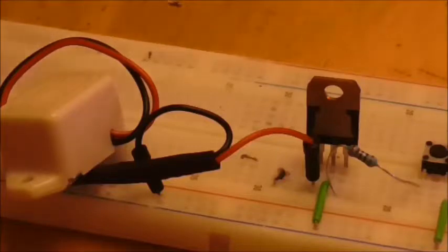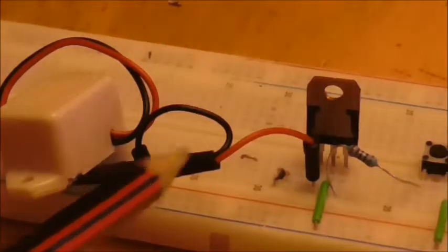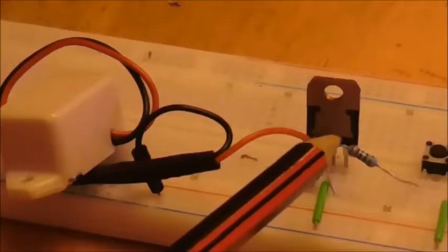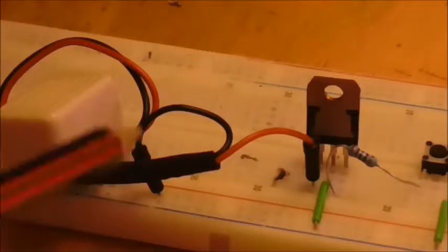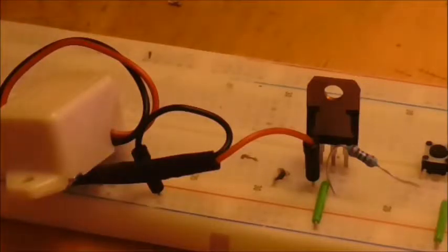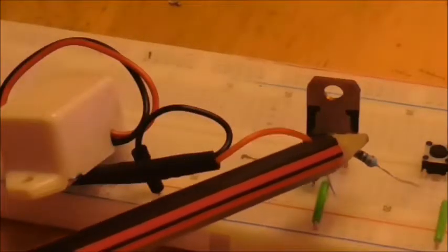And I'd like to point out where the buzzer actually is. The buzzer is hooked in between the emitter of the transistor and the ground of the supply. And when you do this, this is called an emitter follower. You'll get the same voltage at the emitter, but you'll get a little bit of an increase in the current from the collector due to the current at the base. It's not much, but it helps. This thing takes about 30 milliamps, and that's going to help us work out what to put in there.